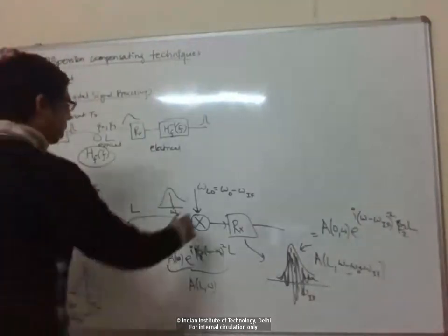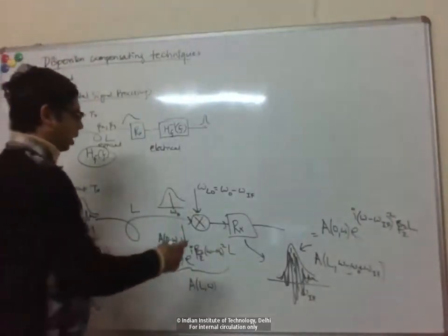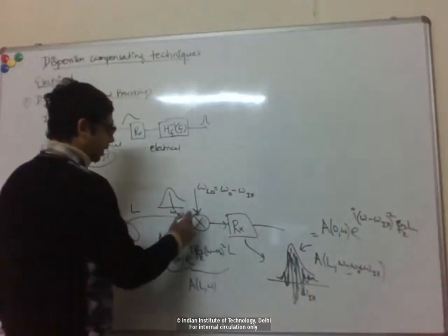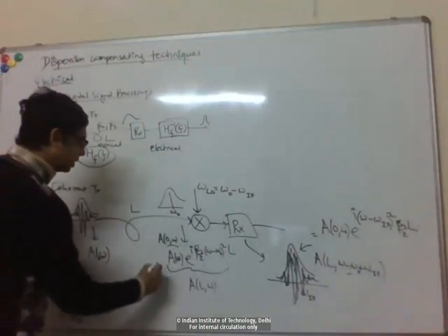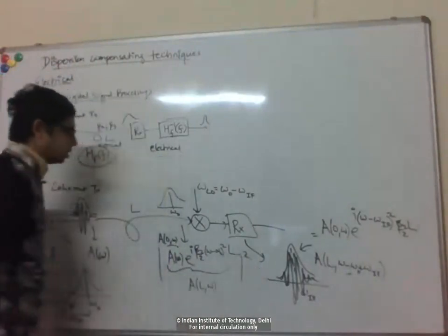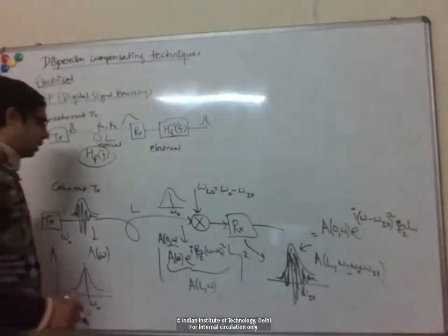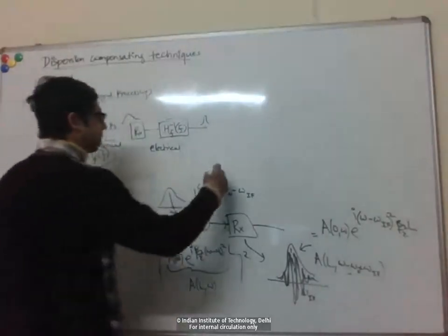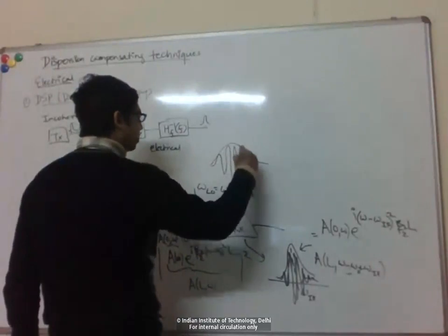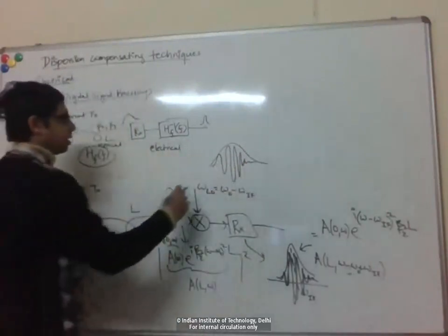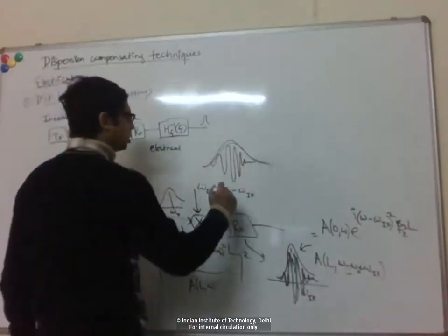So again, there's a question why this local oscillator is used. Again, if I directly photo detect it like this, right? Then what I will measure is the mod square of this. Or in other words, if I look at the time domain, let's say I have some chirp pulse here after the fiber. I will just measure the envelope, right?